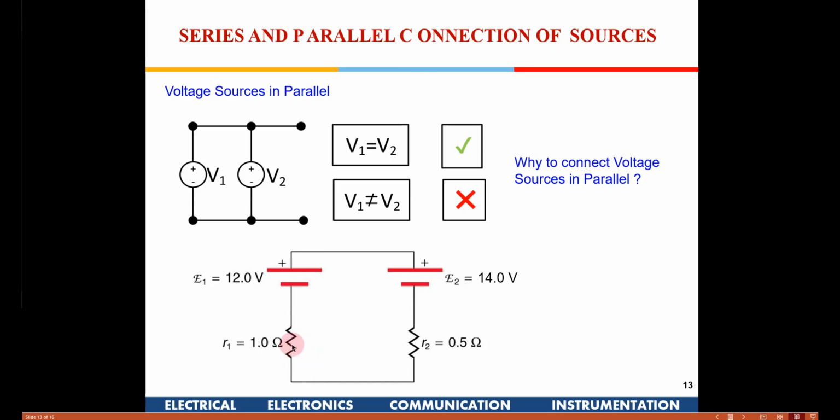It should be able to dissipate that kind of little bit of heat. But if you have a large voltage here, then the electrolyte will start boiling, or your battery might get spoiled. So generally if you have a 12 volt battery, it will get charged to around 13.5 volts. Then you will have 0.5 volt divided by the series resistance, a small current, and a little bit of heating would happen in those batteries, but that is okay.